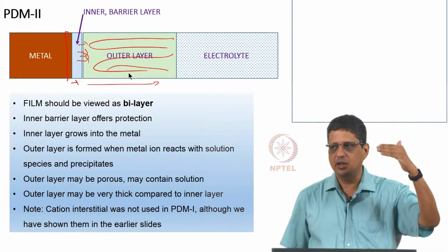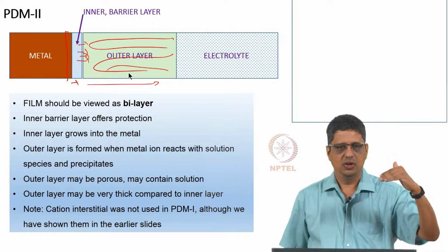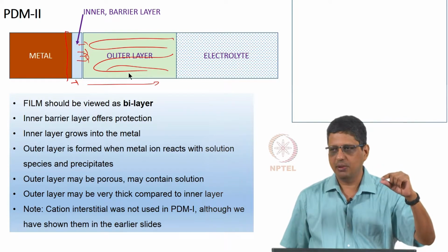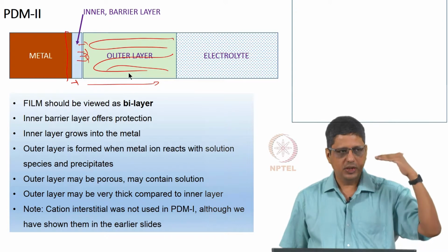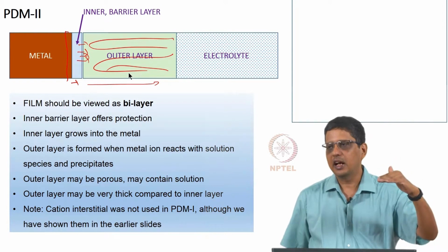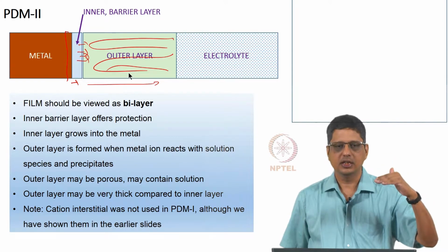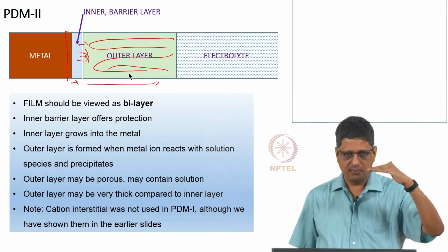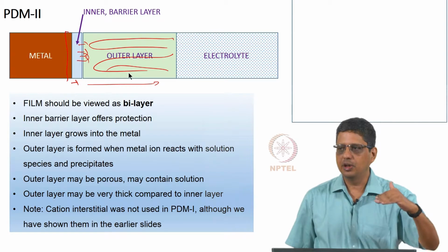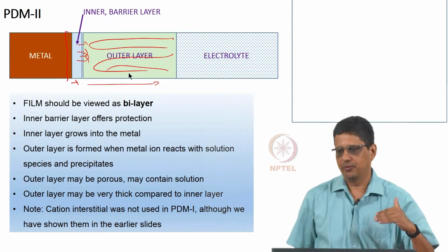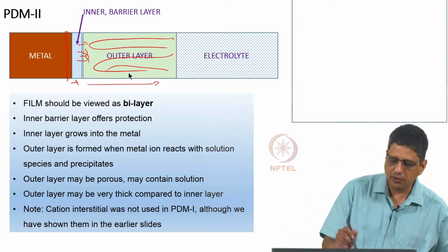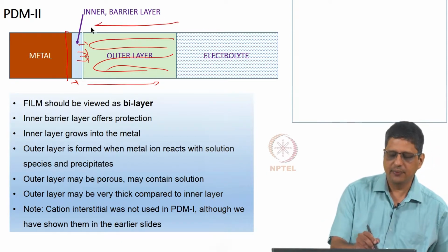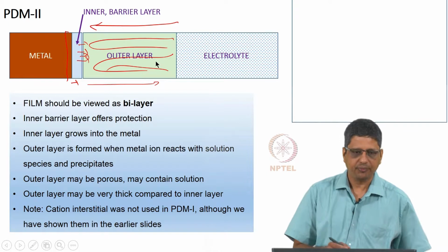Depending on what angle you are using for measurement, you can probe a few nanometers or even a 1 nanometer thickness layer, and then what people do is remove the layer nanometer by nanometer by a technique called sputtering. Okay. So, you can monitor the film composition as you go down from outside to the inside, what is the composition.